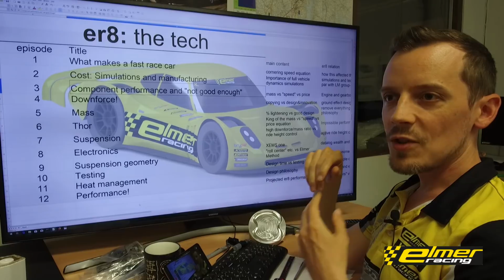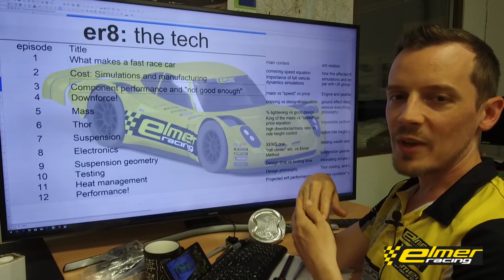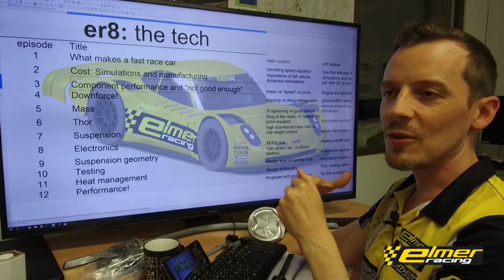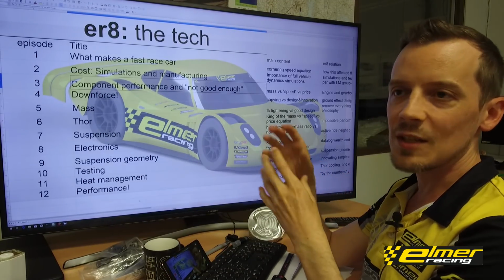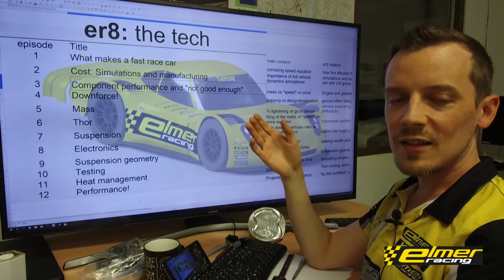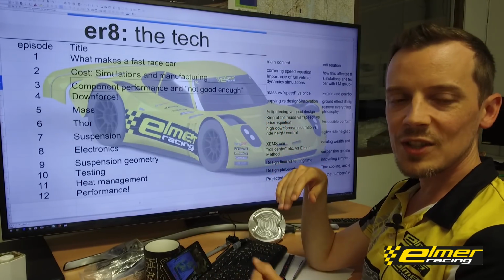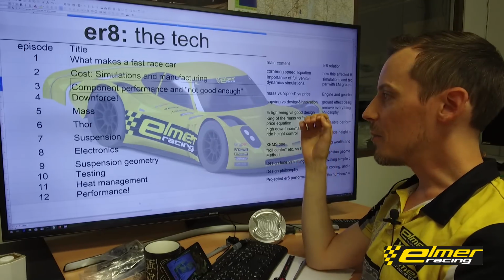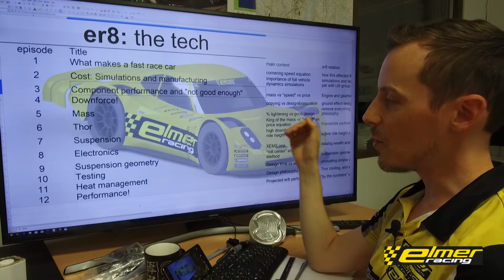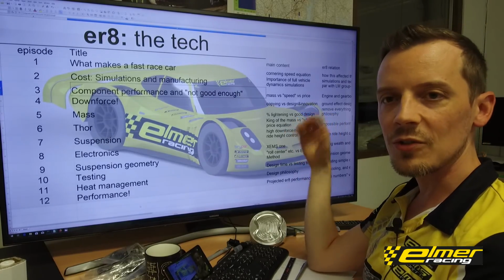But then again, those are not OEM engines, so you spend 1-2 years developing that, and then after that you figure out the valve seats just keep pushing into the cylinder head or something like that, and you're fixed on the design of that because you can't remanufacture it. So for that instance, the OEM aspect of the Thor engine is a very large goodness increase.